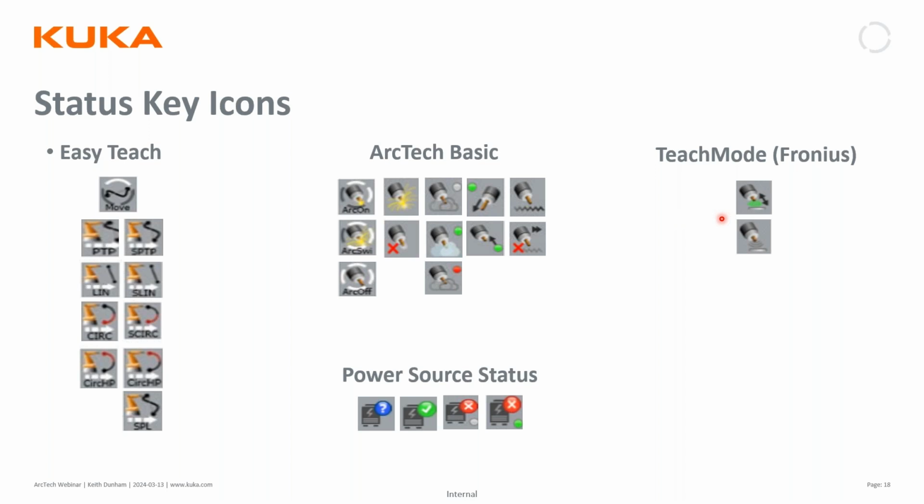if you make any contact with the wire to anything electrically conductive, the wire will retract so you don't bend it, and then it'll maintain that stick out. Once you aren't touching that part, the stick out will go back to where it was. So that's kind of handy for online programming.